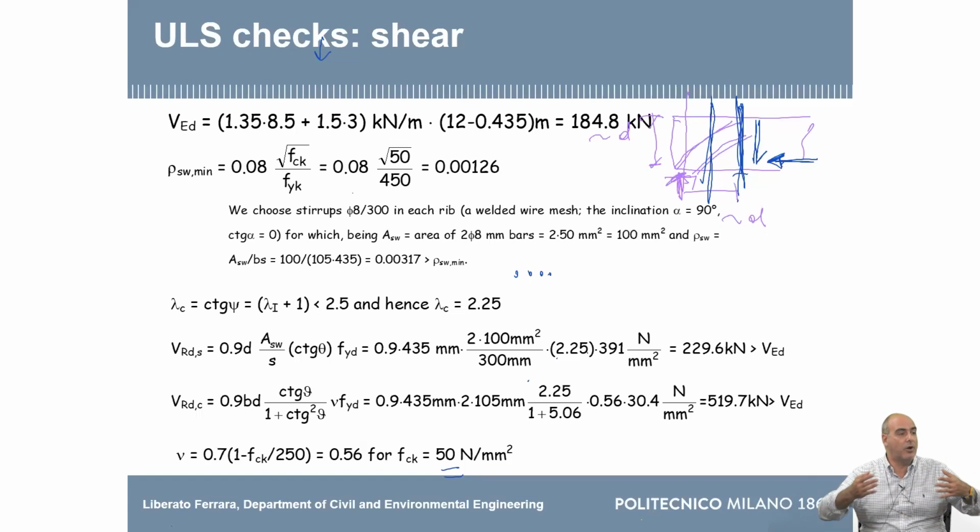Ductile mechanisms occur with large deformation, so give us a warning. Brittle mechanisms occur without a warning, so we want to avoid them. This is not exactly the capacity design, but these concepts are those which inform the capacity design as well. So in some cases, we over-design the brittle mechanism so that the ductile mechanism, of course, works. But this was not the case.